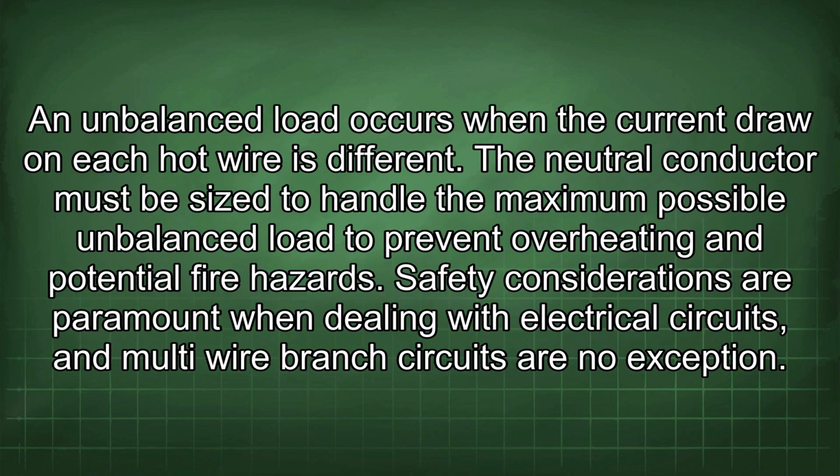An unbalanced load occurs when the current draw on each hot wire is different. The neutral conductor must be sized to handle the maximum possible unbalanced load to prevent overheating and potential fire hazards. Safety considerations are paramount when dealing with electrical circuits, and multi-wire branch circuits are no exception.